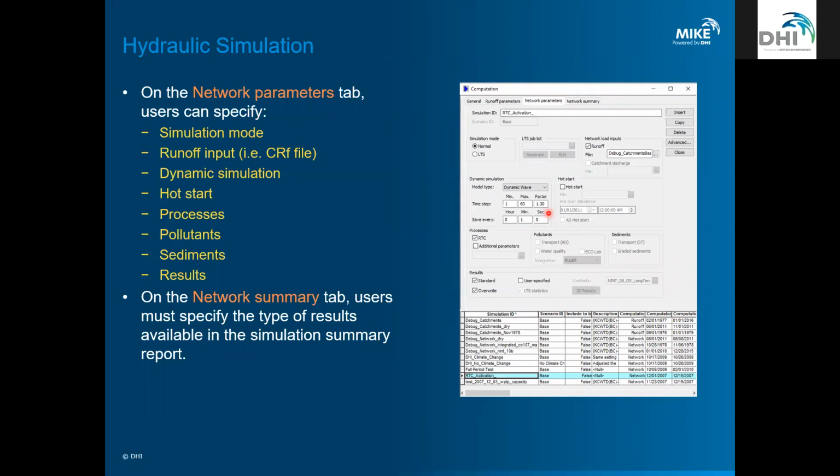If you choose larger time steps, it's going to be less in depth in your results, but depending on what you're focusing on, if you have a very specific instance that you're looking at and you want to see how a rainfall event of 3 days responds, I would recommend doing a specific model just for that over the course of an entire season, and then you can get a very specific time step and a very intricate look at what's happening.